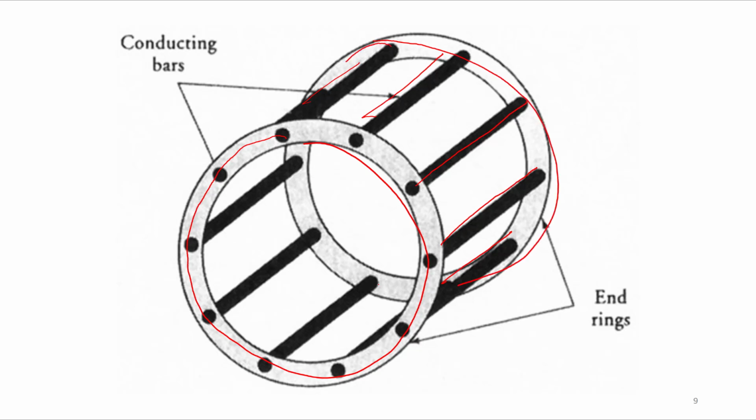The benefit of this is, as soon as it is put and designed like this, another flux will be created which rotates on the rotor surface itself at the synchronous speed. That will try to catch the stator poles, which are rotating at the synchronous speed. So gradually it will start moving. When it starts rotating, finally it will lock at the synchronous speed.